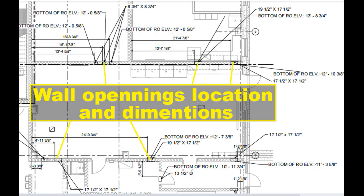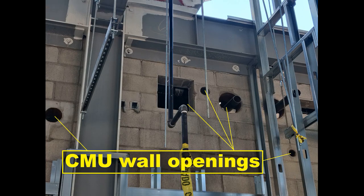Utilize bending details that conform to the requirements of ACI SP-66. No approval will be given to the shop drawings until the contractor certifies that all openings, including those for mechanical and electrical service, are shown. If, during construction, additional masonry openings are required, resubmit the approved shop drawings with the additional openings shown along with the proposed changes. Clearly highlight location of these additional openings.